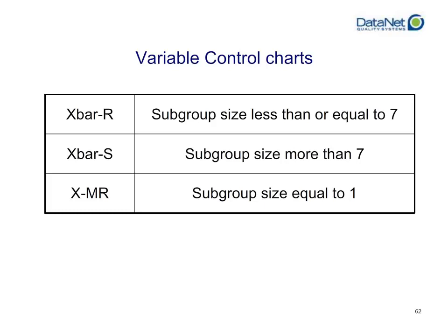S in this case refers to standard deviation, where it plots the standard deviation for the subgroup that you've just plotted. That tends to work better when your subgroup size is greater than 7. And again, your mileage may vary if you are from a different school of thought or your process is a little different. Maybe you don't want to switch to an Xbar and S chart until your subgroup size is 10 or 9 or whatever works for you.